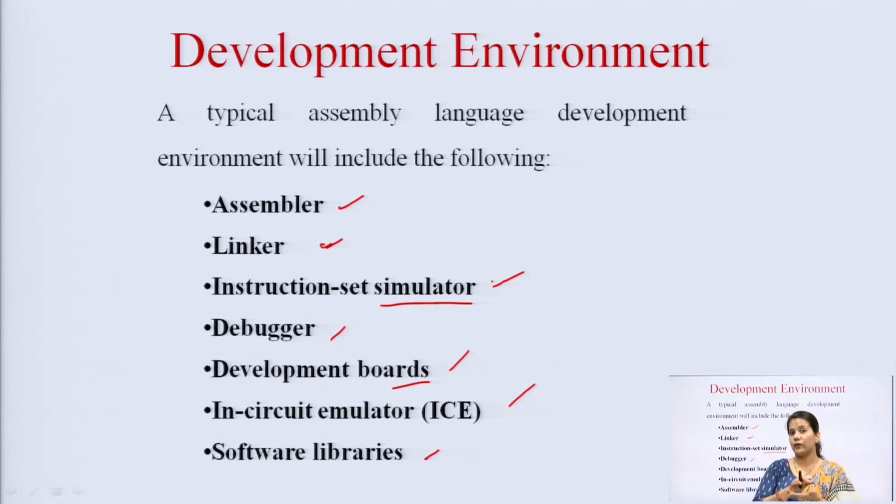That is not an extra part, that is the essential, integral part of the processor environment, needed for the embedded application. That is known as the development board: a board on which the main processor chip, along with the different peripheral ICs and control circuitries, all the required circuits, are available along with the processor IC.